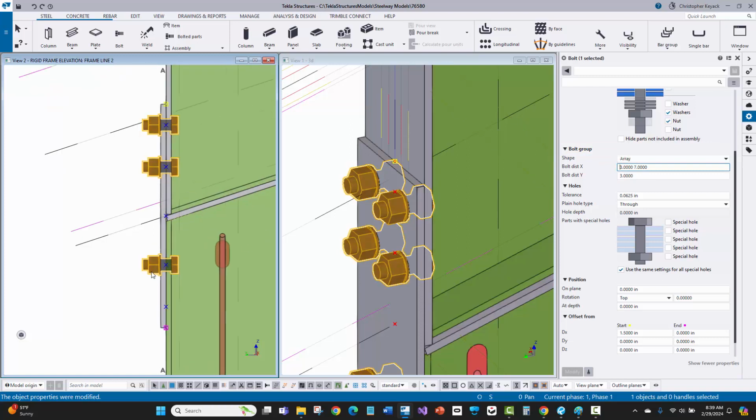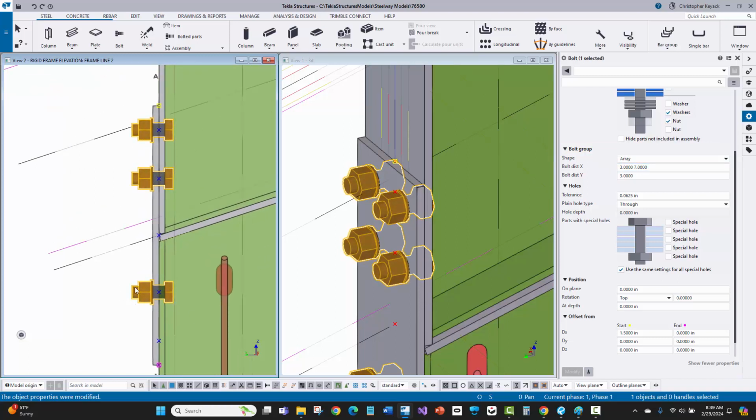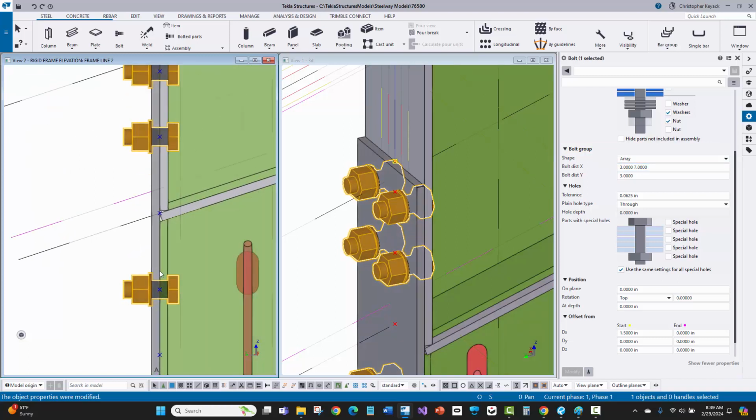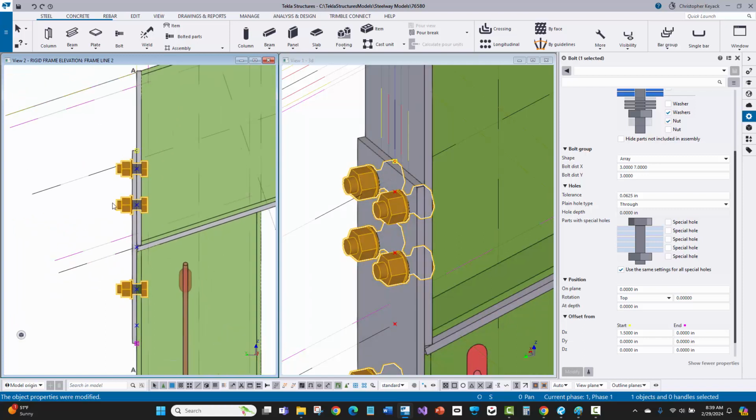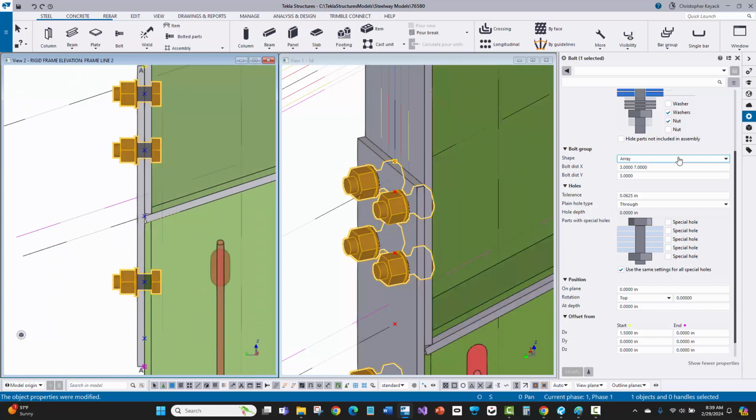And then you can see that. Now, technically though, there's kind of a gotcha that I got to watch out for. These holes are not really going through that material on the column, and it's misleading. Because really I'd only pick these 2 parts up here to do the initial bolting on this particular piece. And so those bolts can't extend down there like that in the same bolt group. So I'll just actually remove that and just say enter.